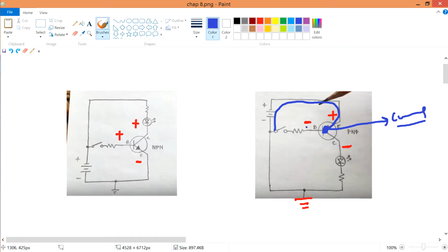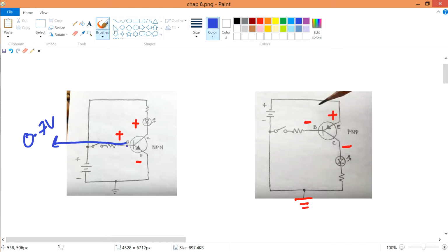So this is another way of allowing your load to receive voltage or current. But the end in mind is that your base voltage is 0.7 volt. The current, I don't know, it all depends, because if you remember V equals IR, it depends on your resistors and on what current you want to input. In any case, your base is from your Arduino, while you have another power supply.